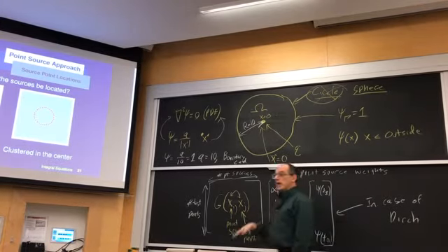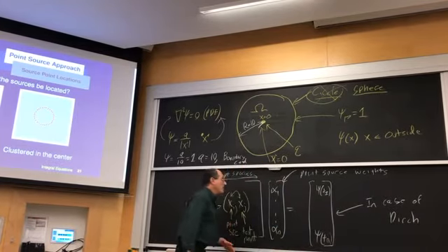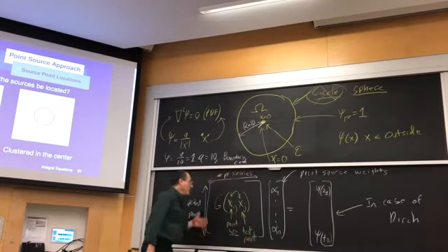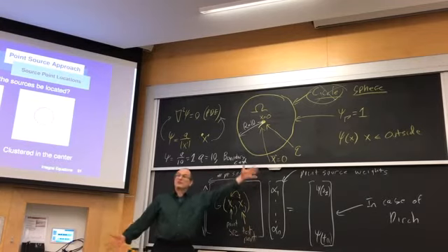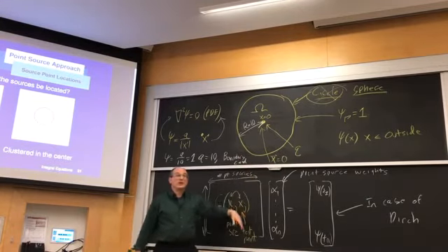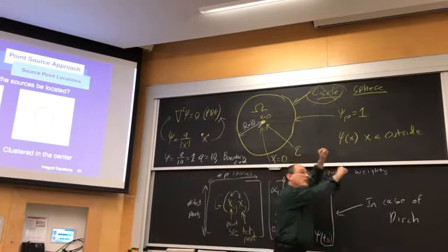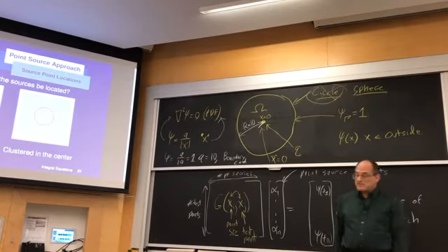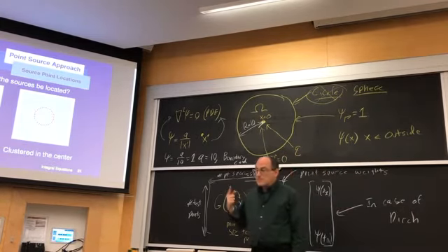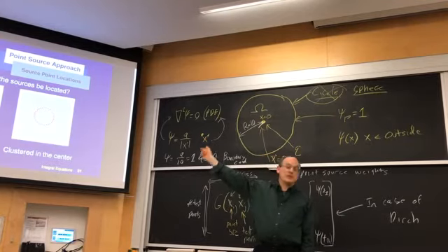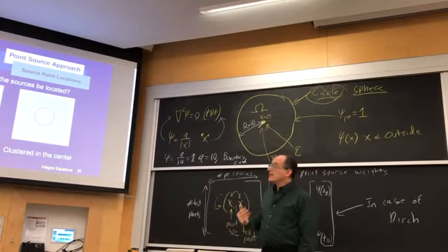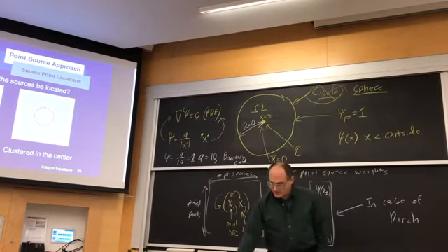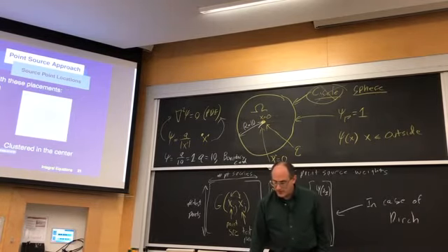It means that if the matrix is ill-conditioned, you may have test point values that are 1s and 2s, and you may get weights being 10 million or 100 million. So one weight is 100 million, the other one next to it will be minus 100 million. And then you'll get weird errors because of that. So these methods have all these different names. They're called desingularized methods, there's a whole bunch of different names for it.